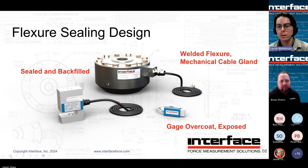You see here on the left, SSM, that stands for a sealed S-style load cell. And it basically has a cable gland on one side, and then that internal cavity where we have the strain gauges, we backfill that with a gel potting compound, and that helps seal the bridge from any moisture ingression. Then, on the other side, the right side there, the MB, that's pretty much exposed.